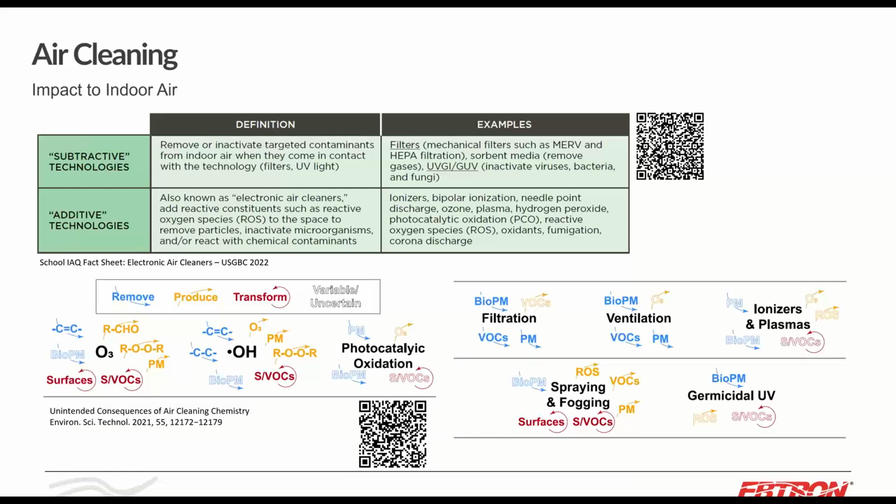Ozone by itself, which is the O3 on this table, is naturally occurring. Every time there's a lightning storm, there's more ozone created. There's ozone in the atmosphere, and it's very good at removing poisonous UV rays from the sun, right? However, ozone within the indoor space has a negative effect on health, because it changes the indoor chemistry. It interacts with different things that are floating around in the air, different chemicals, different VOCs in the air. And it also reacts with oils on the person's skin and can cause multiple reactions.